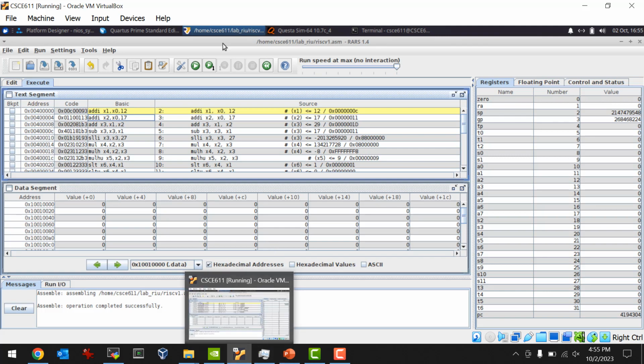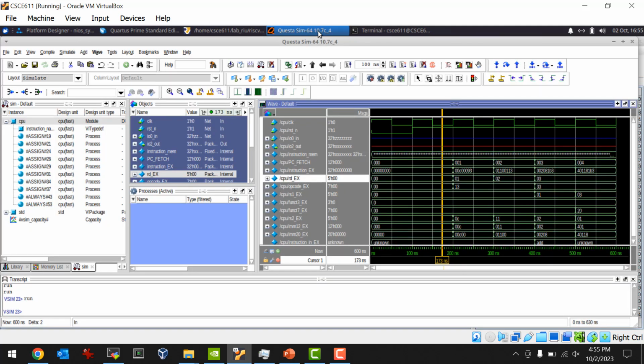And speaking of the register file, I don't have that in here, so I can't show you that. I didn't add the register file yet. But once you put the register file in, you can look at the contents. You can drill down into the register file and add the memory. It's called mem or something, the signal that's declared that holds the 2D array of bits. Just put that in ModelSim and you can see all the values updating. And there's only 32 of them, so you can fit 32 registers on your screen here. With the instruction memory, it's too big.